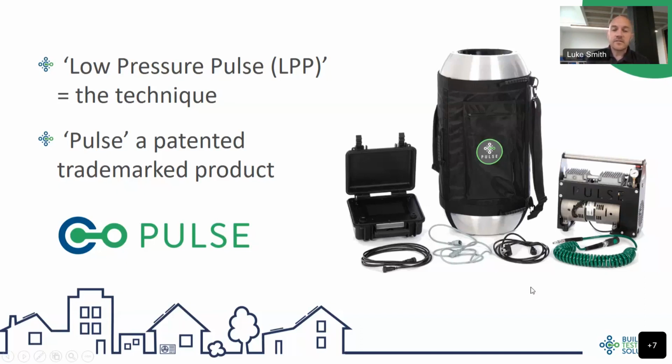So here on the screen, you can see an image of where we are today. Rather than the piston method that was originally developed, and obviously all the testing that was done on a garage compressor type configuration, we've now streamlined all of that switchgear into what you see on the screen, which is a nice portable, professional-looking unit: a compressed air-based portable compressor used to pump up the air receiver, that canister in the middle, and then the controller on the bottom left there, used to control and execute the test itself. And that controller is what's used to record the background pressure in the room as well.